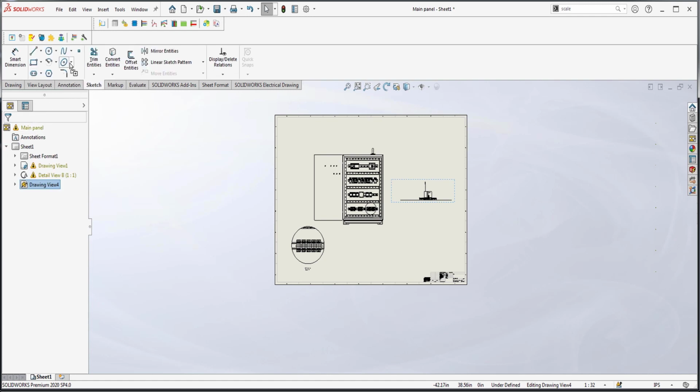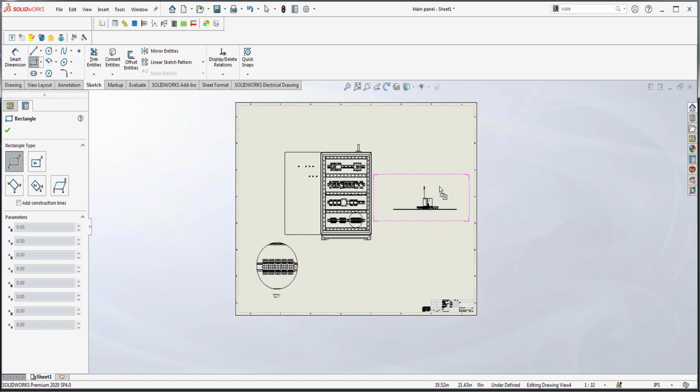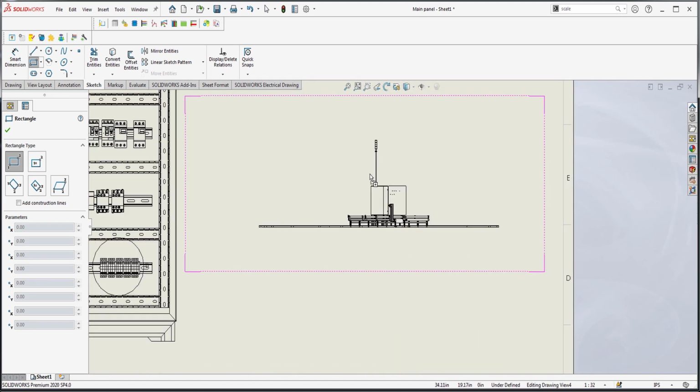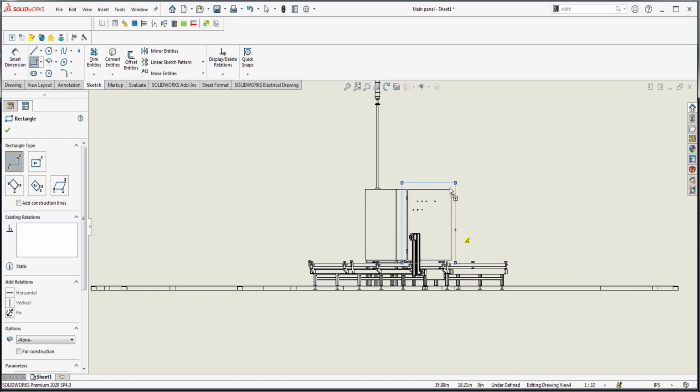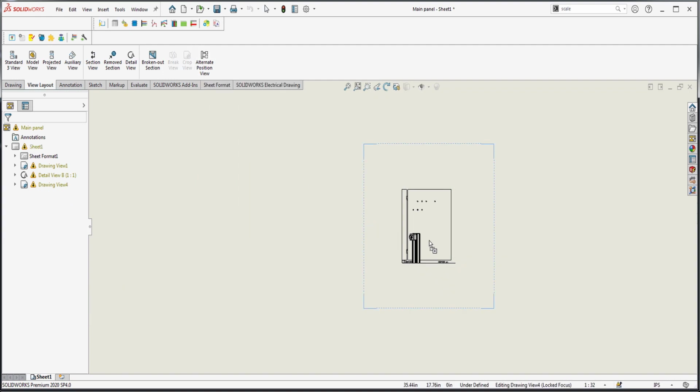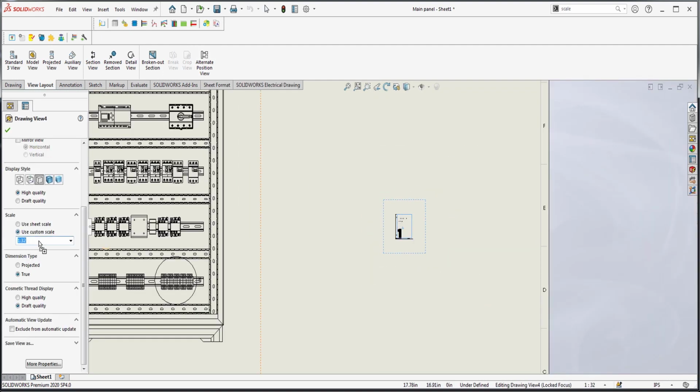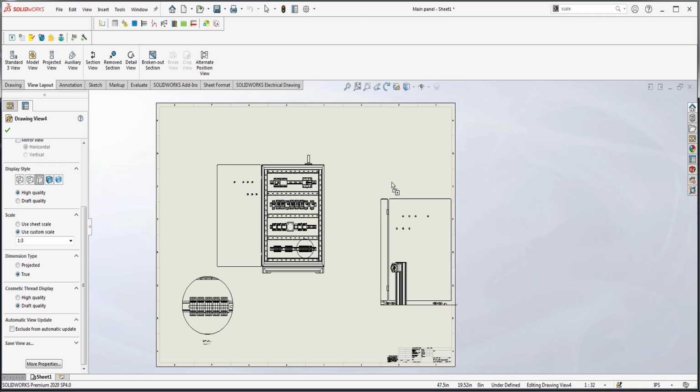Now, of course, I may have some stuff that's in the way. And you'll notice that here. I'm going to zoom in, grab that door, and take a picture of just that view. I'm going to just crop it to that view of the door to be able to see this. Now, this is great for Lamicoid tags, but it's also great for placement of push buttons, because the placement of your push buttons, as you know, are very critical when you send it off to the panel builder, that you want to be able to give them the exact cutouts of your door or the exact layout for where these buttons should be at.